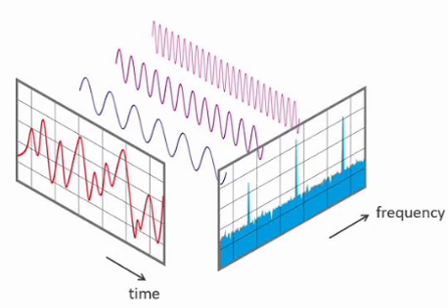The realization of linear phase FIR systems: if the impulse response is symmetric about its origin, linear phase results. If all-zero filters have a linear phase response, a special non-recursive structure that reduces the number of multiplications by approximately one half can be implemented. The impulse response for a causal filter begins at 0 and ends at m minus 1. As discussed, a linear phase FIR filter of length m is characterized by h of n equals h of m minus 1 minus n. The symmetric property of linear phase FIR filter is used to reduce the multipliers required in this realization.